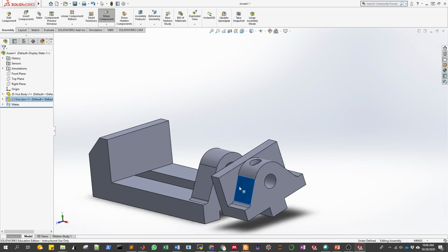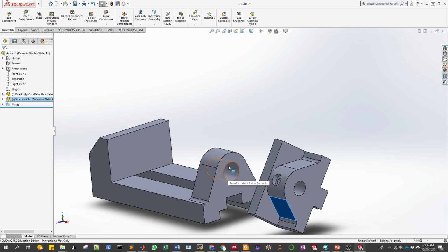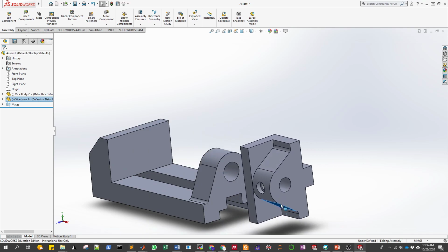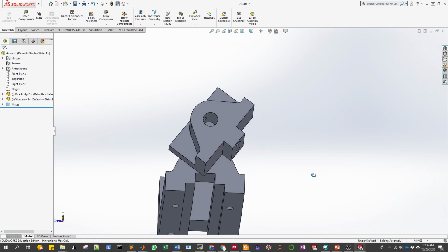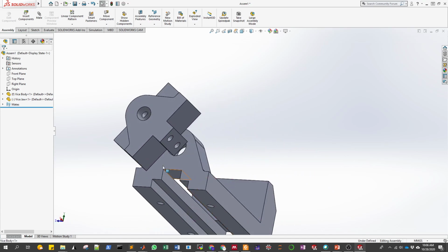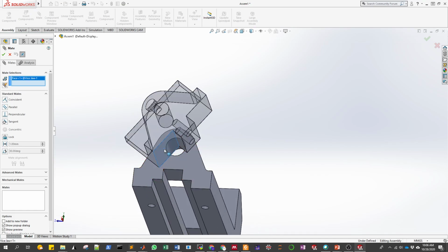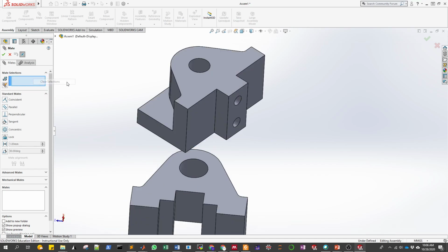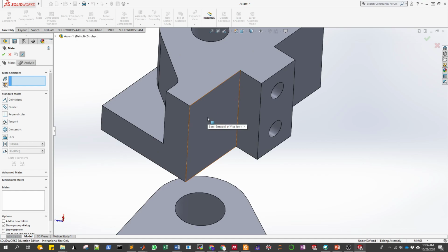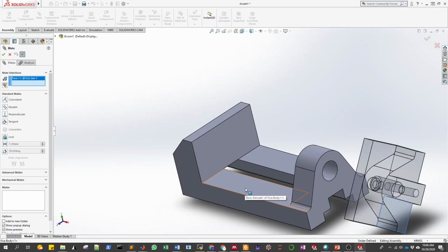But you will see that this jaw can move anywhere along the axis of the center of this cylinder. They are aligned only in those two circles. So what I need now is to define that. Maybe I can say that this face here in the bottom of the jaw, and I'm gonna select it again, this one, is gonna be parallel to this one right here.